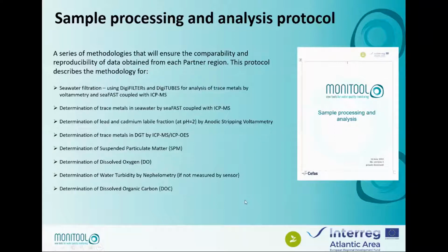So the protocol describes the methodologies for seawater filtrations using DGT filters, DGT tubes, determinations of trace metals in seawater by ICP-MS and by volumetry, and determinations of trace metals by DGT by ICP-MS, and also determinations of various physical parameters like suspended particulate matters, dissolved oxygen stability, and dissolved organic carbon.